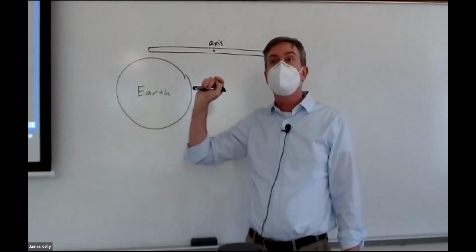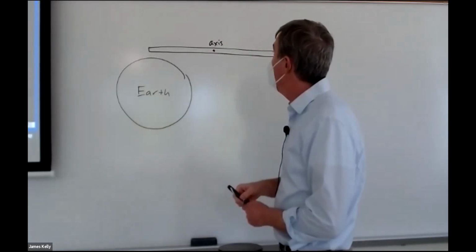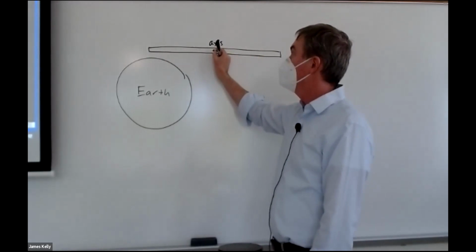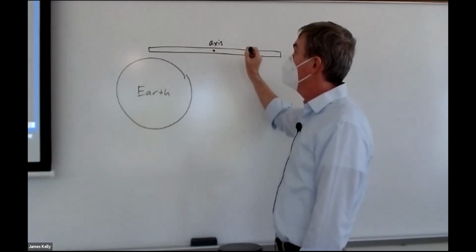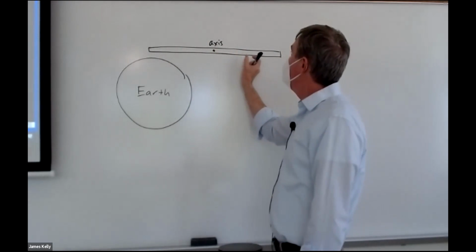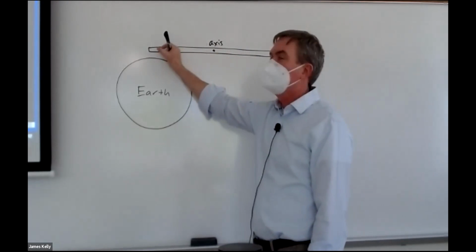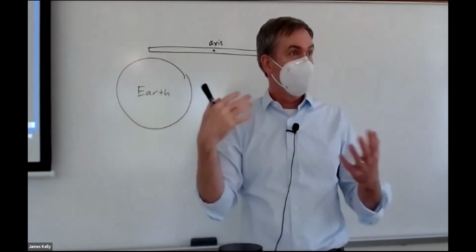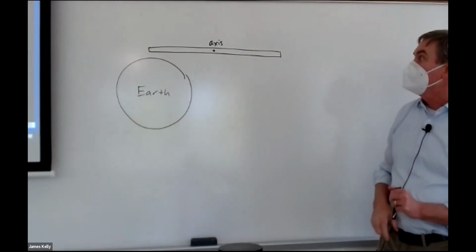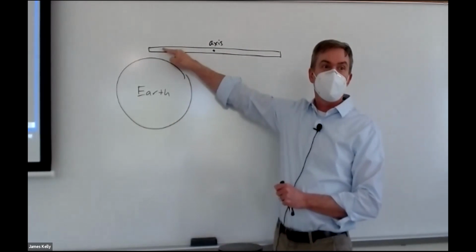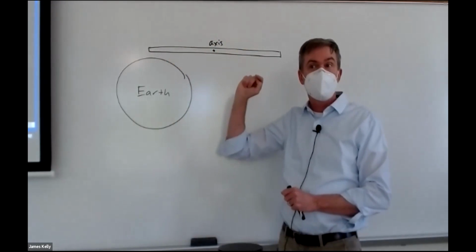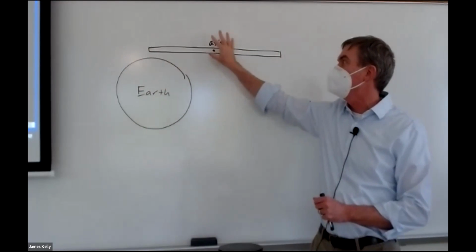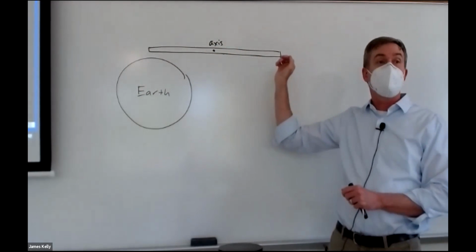The center of gravity is finding out where the gravitational force acts. Instead of replacing all the mass with the mass located at a point, we think of lots of little forces on all little bits of mass. Where could I place one force so that the overall dynamics don't change? In this case, I would have to place that force near this end, and it wouldn't be at the same place as the center of mass. So the only place where they differ is when the gravitational field over the span of your problem really changes a lot.